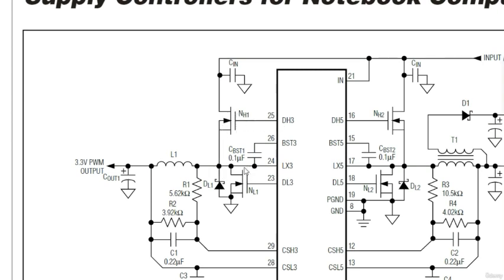As you see, we have another MOSFET here. We have drive low 3. This is the control signal on pin number 23. So here the 3 volt will be generated and pass through this coil, L1, and then through this chemical capacitor. This is a filtering capacitor, and then we will get the 3.3 volt power management output. This 3.3 volt will be applied to the Super I/O, or Super IO, and then to the BIOS, to the keyboard, to the power button, etc.